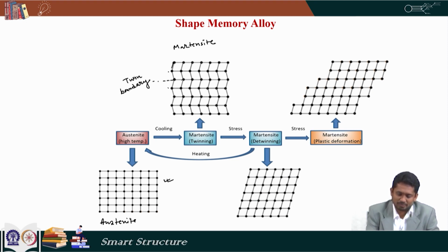At this twin boundary, the structure does not break, it just shows a twin shape. Now, if I compare the overall dimension of these two, if this is L0, this is also more or less L0. So, macroscopically they are the same, although microscopically they are different.